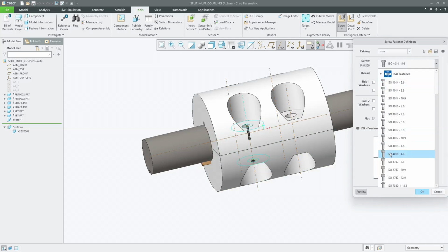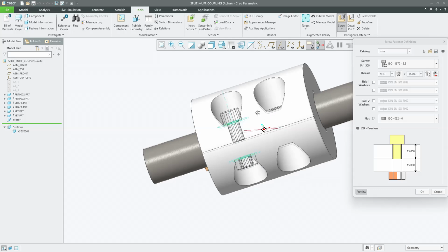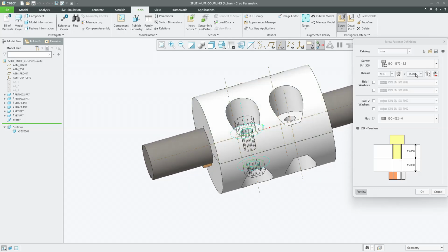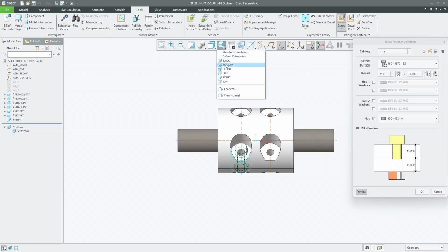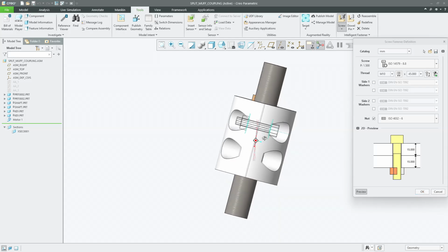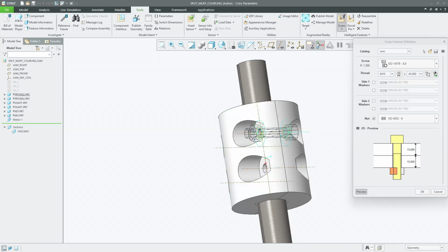In this, I'm going to select fastener is ISO 14579, and I'm going to have M10 bolt here where it looks fine, and just click OK. So the total length of the bolt is not matching till the nut, as we can see in the section view here, left side. So I'm going to increase the length of the bolt as 35, even bigger, 40. Yeah, 40 looks much good where the thread engagement is also fine and the clearance is also good.